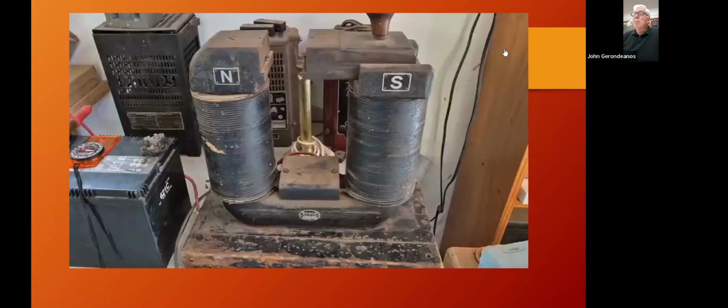And with our access to really big car batteries or even better DC arc welders, we don't have to worry about this too much. So the conclusion is, with a car battery, you'll probably get about 30 amps. And with a DC arc welder, you probably get somewhere between 160 and 200 if you really want. But from 60 amps to 100 amps would be more than adequate.